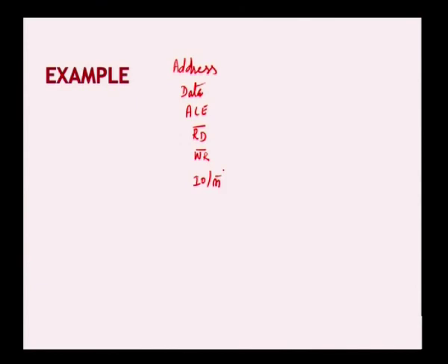The bar represents that this is an active low signal. Active low and active high signals are generally used because these are binary terms. Active low means it is activated by applying 0 volts. Active high means it is activated by applying 1. 1 represents plus 5 volts, VCC, and ground is 0. So, when we apply 0 volts, the active low signal will be enabled. When we apply the high level, that is plus 5 volts, automatically the active high signal will be enabled.